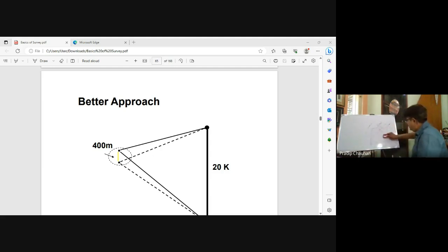So this is all about linear survey, because the levels are also equally important. Now, how do we get levels with more accuracy nowadays when you are moving the total station? If this is my possible alignment of the road, then with the use of DGPS, we are using the time factor, giving more appropriate time. You are using control points. These control points might be at a distance of, say, 5 kilometers each. These control points have very high accuracy in X and Y direction, as your rover and DGPS system have been kept for a few hours or even a few days.